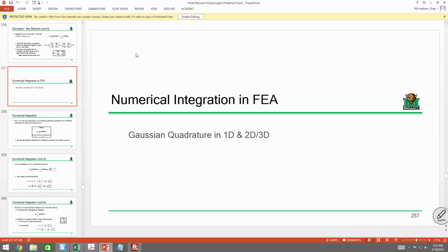In the world of finite elements, if you're ever doing any research on the topic and you hear the term C0 continuity or C1 continuity, C1 continuity elements are elements like beam elements where you have to match not only the displacement but the derivative of the displacement. Bar elements are C0 elements. You only care about the displaced shape. More elements yields a more accurate result. So that's sort of how that works. All right, everybody good? Okay.